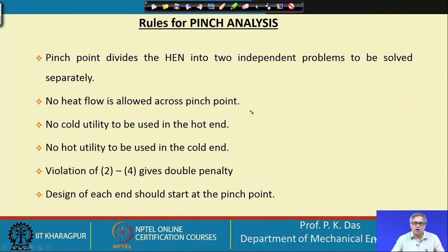So, we have one hot solution and one cold solution, or rather the hot end of the network and the cold end of the network. No hot utility, no cold utility is to be used in the hot end. Similarly, no hot utility is to be used in the cold end. So, we have three rules.